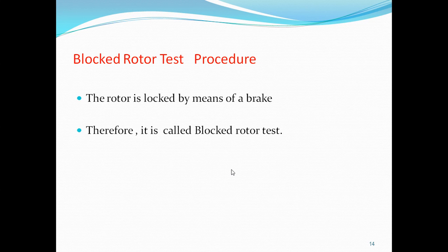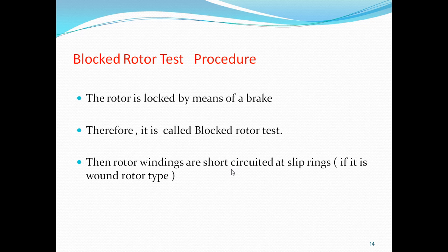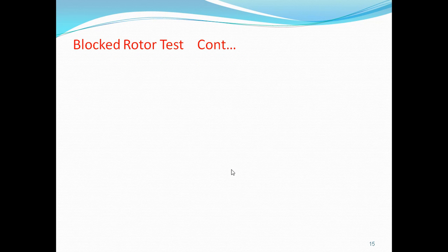The rotor is locked by means of a brake. Therefore, it is called blocked rotor test. The rotor windings are short circuited at slip rings, if it is wound rotor type.